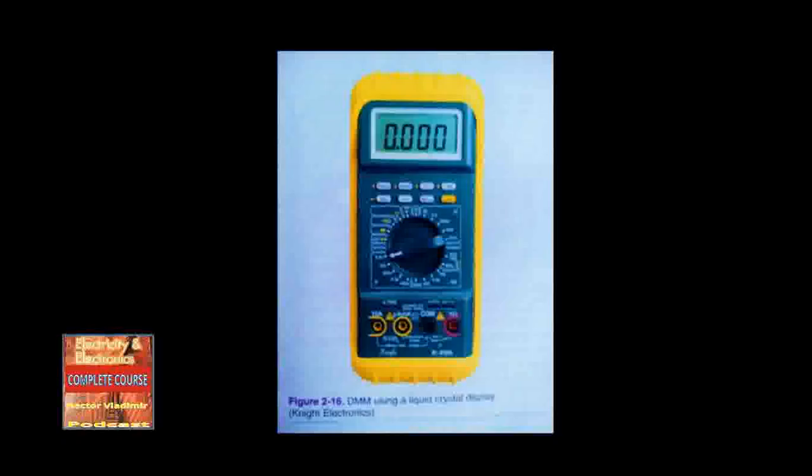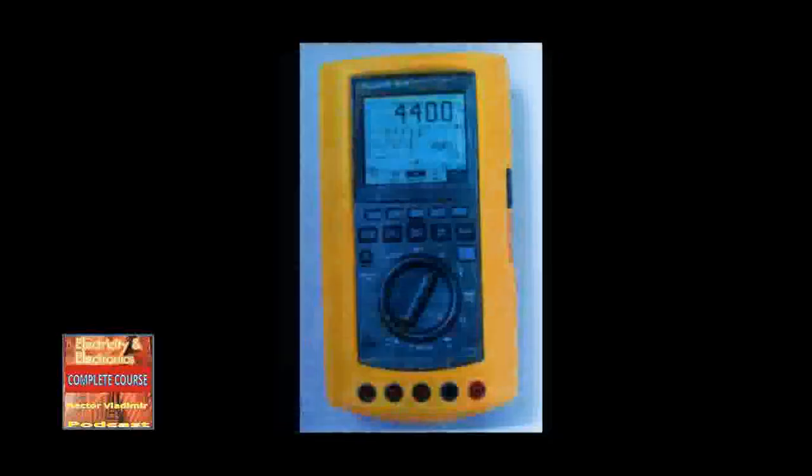The liquid crystal display shows the meter reading in digits rather than on a scale. Some DMMs simultaneously display digits as well as a bar graph that simulates a linear scale reading. Figure 2-17. Digital meters not only measure volts, ohms, and current, but also can test electronic components such as transistors and diodes. Figure 2-18. The digital multimeter can come with a rotary dial, like the analog meter, to select functions, or a keypad that is pressed with the fingertips.